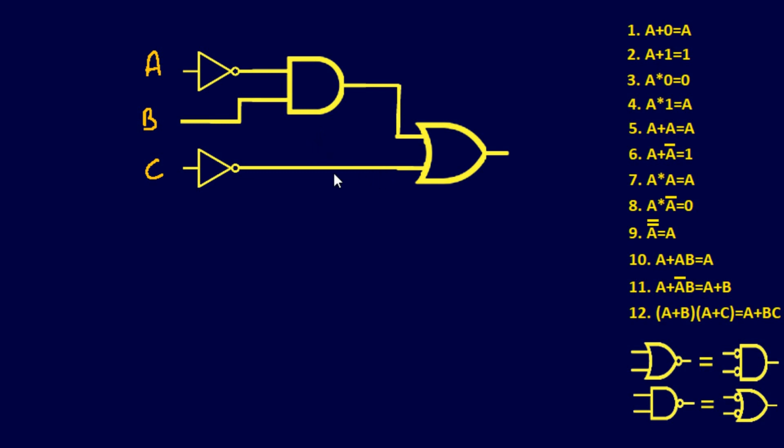So, I want to go ahead and start at this end, just because I'm favoring this end. Go ahead and add a NOT there, and a NOT here. So I just now created one NAND gate. And we also want to create a NAND gate here, so let's see if we can do a bubble there, and then a bubble down here. So that's awesome. Because looking at this, by me having a NOT right here, that actually cancels out that inverter, or that NOT gate.